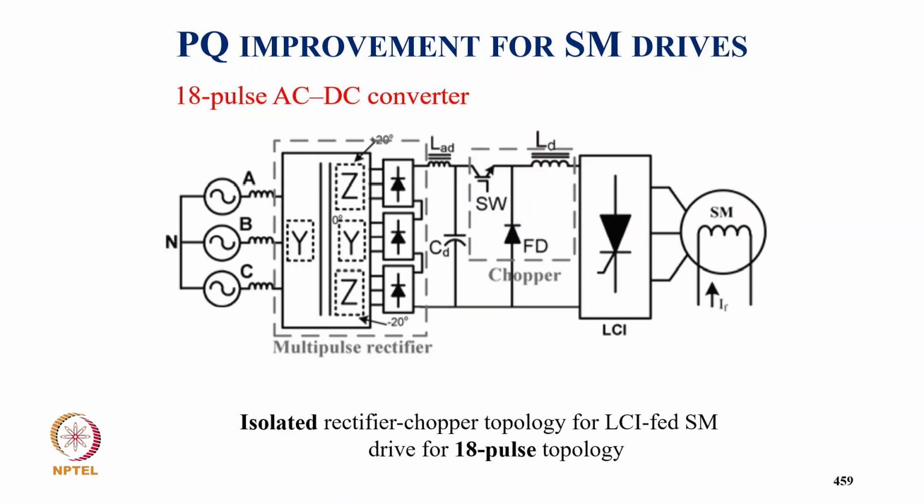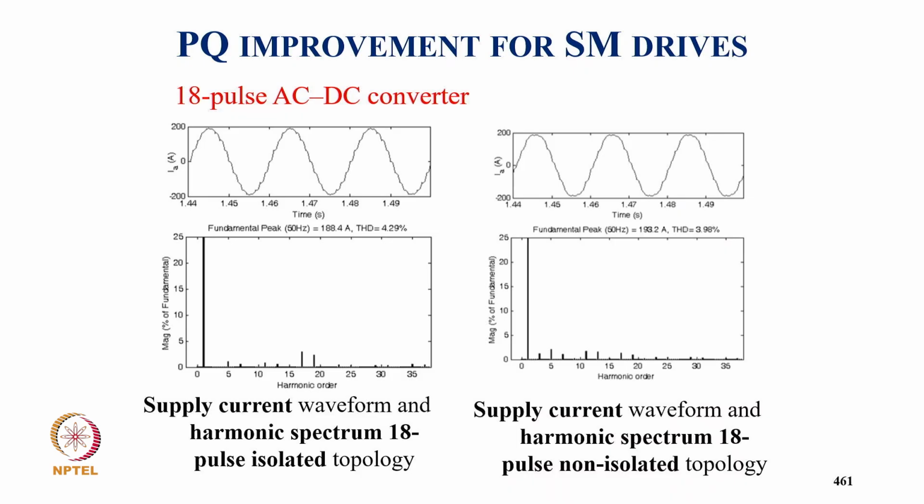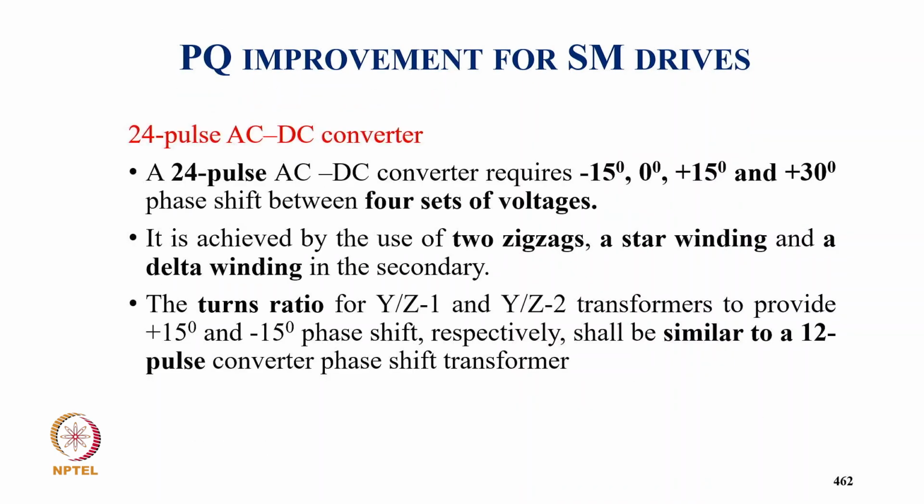And this is typically an 18 pulse converter with the direct rectifier with the buck converter feeding the LC to drive the current source. And this is another configuration of a typical 18 pulse topology with the buck converter, and the THD here is considered less than 5%. You can see at light load as well, even in the isolated and non-isolated boost topology.